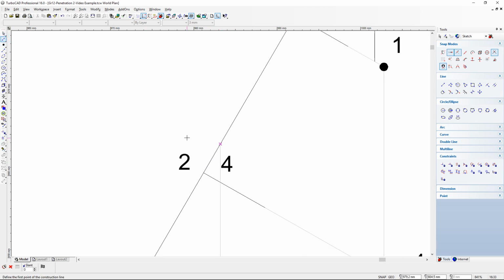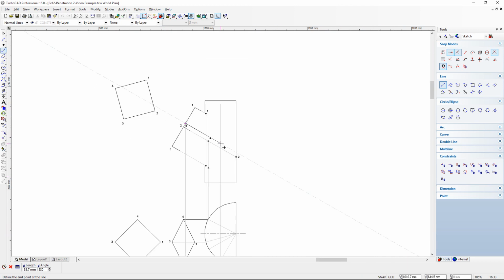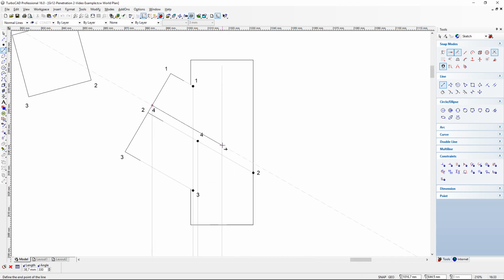And now we also need to follow the same angle. As we saw, this one was 330 degrees, or a slant of -30 that we have to draw from that intersection. So I'm going to go 330, and that will give me the angle at which I must project this construction now towards this projection that came from the top view.